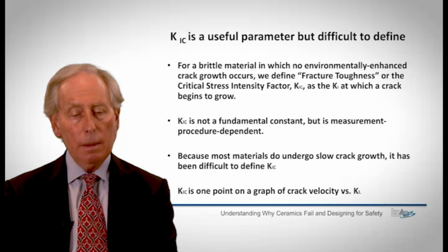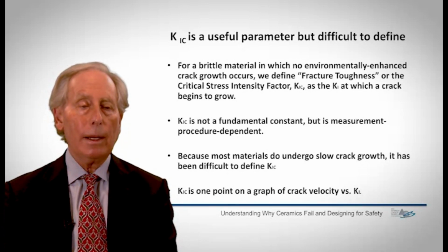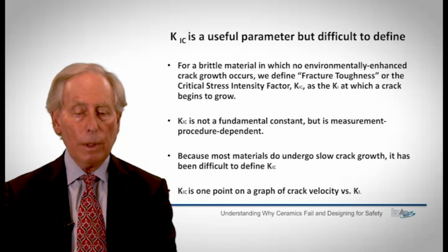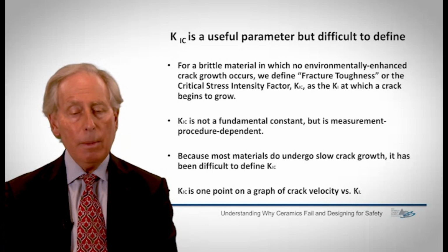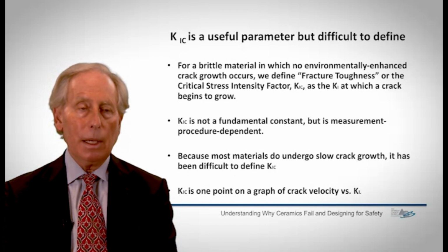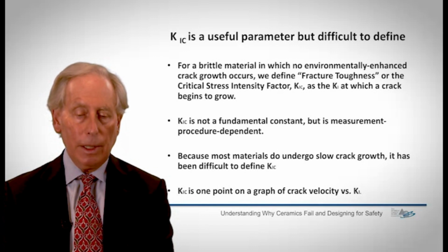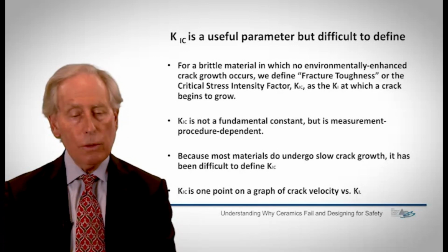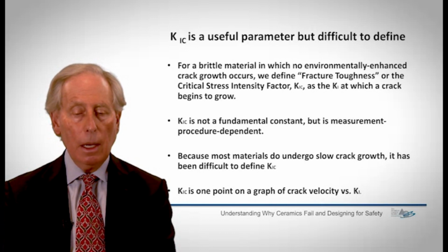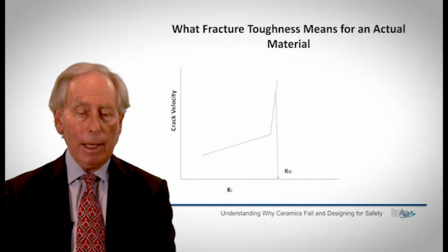And because most materials do undergo, I showed up here, I said if there's no slow crack growth, what I call environmentally enhanced crack growth, slow growth with time, then this definition works well. But for many materials that do undergo this, then that's a problem, because then there's a slope to the curve and we have a little more difficulty. And so then critical stress intensity factor becomes 1 point on a plot of crack velocity versus K1. And I show this schematically as follows.